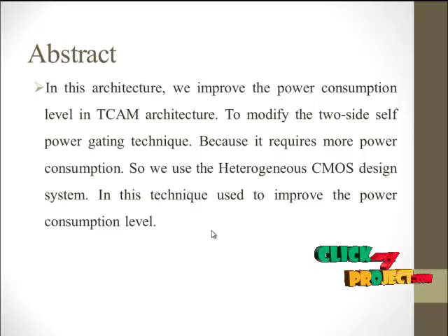A binary CAM stores and searches only zeros and ones. However, binary CAM cannot satisfy fast commercial applications, and its utility is limited. A TCAM can store and search an additional state called don't care, so that a TCAM can perform partial matching. The TCAM has the ability to find the longest prefix match by comparing the search data with its cell contents to find all matching prefixes and determine the longest prefix in one clock cycle.